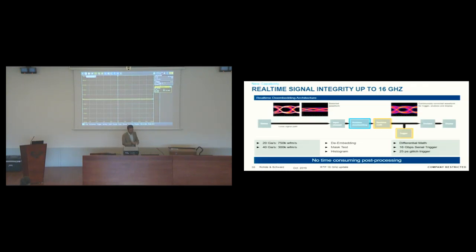So I'm connecting these cables. This is a matched pair cable that we provide for the TDR measurements. They are especially manufactured to be electrically the same length. It's a matched pair cable. But anyway, they have the frequency response in magnitude and phase, and we will de-embed as well.